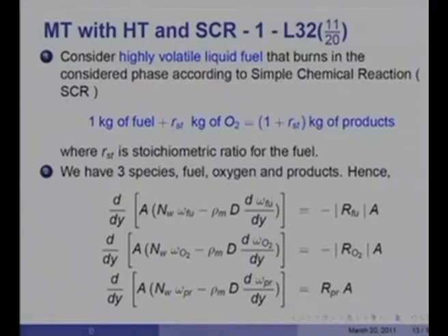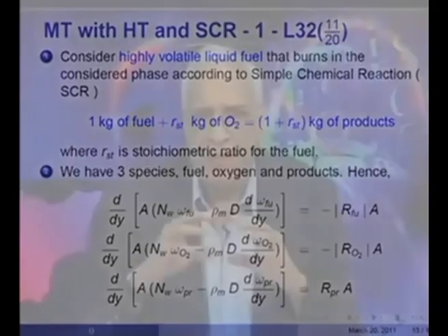Now, what is a simple chemical reaction? Let us consider a highly volatile liquid fuel that burns in the gas phase according to the simple chemical reaction, SCR. Liquids usually burn by first evaporating into the gas phase without any change in composition, that is, the chemical formula of the fuel does not change when it comes out in the form of a vapor, but then it burns in the vapor phase as a homogeneous combustion.